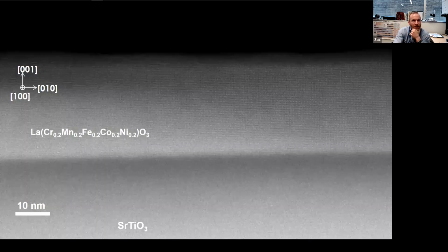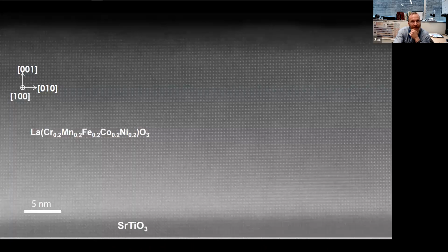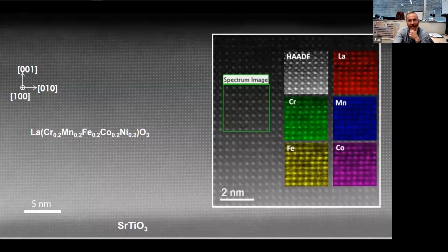We'll do a couple of glamour shots here, doing cross-section TEM, zooming in. And again this time we're going to do EELS, and we were able to do column-resolved EELS. You're seeing all of these elements lit up. What that says is you're looking down the column with the electron beam, and on each of those sublattice columns you have all of these elements. That just means we really are very well mixed, no clustering.